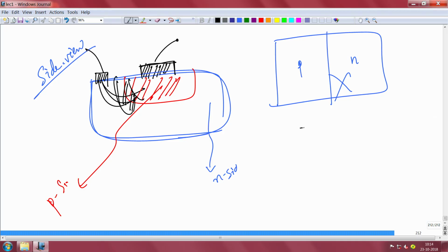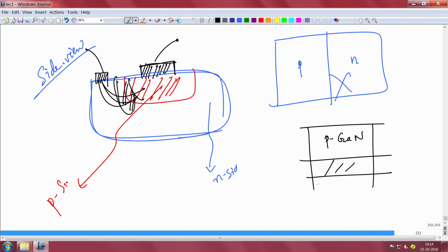For example, in an LED, you have p-type gallium nitride. Gallium nitride is the material that is used to make the blue LED, by the way. The blue LED actually is the white LED eventually that you buy from Philips or any other company, right? So it will be P, then some layer in between, and then an n-type GaN here. You put a contact to the p-type GaN, and you have to make a contact to the n-type GaN also. So what you do is you etch it down.